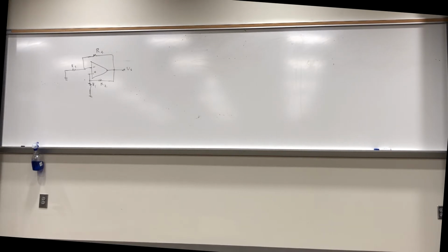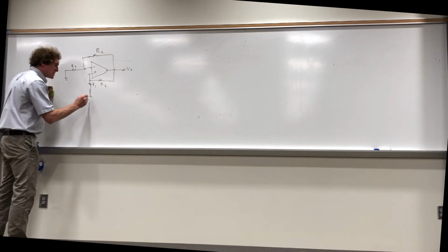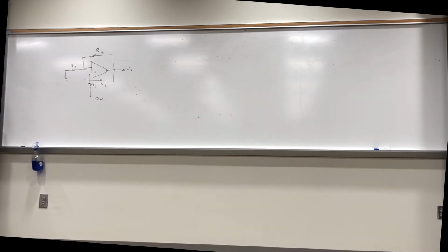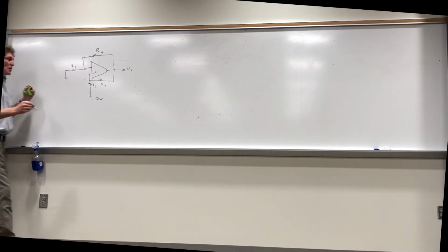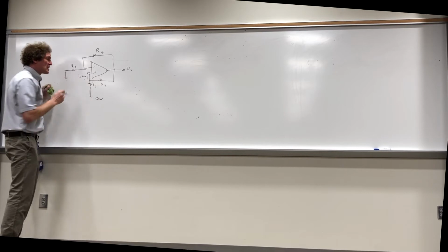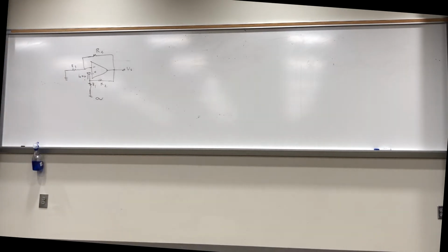Now what we're going to do is analyze an operational amplifier circuit with 4 resistors. But now our goal is just to find the output. There is no input voltage. Got me? All right, now work with me on this. We know that the voltage here is 0 volts, right? Are we in agreement with that? The next thing we also know is that no current flows this way. I is 0, correct, class? No current flows in the plus terminal, correct?